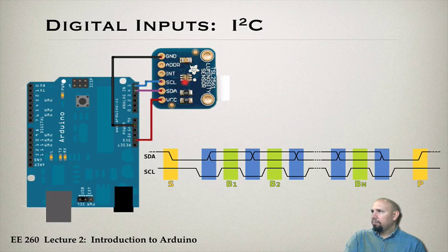And so this is a sensor, and as a sensor, it needs voltage and it needs ground. In this case, this sensor needs 3.3 volts. So here it says 3V3, that's actually the voltage, 3.3 volts. And so this sensor needs 3.3 volts and then ground. So that provides the ground. And then it also has these two signals that are connected to it.